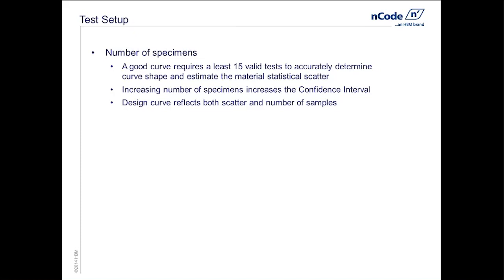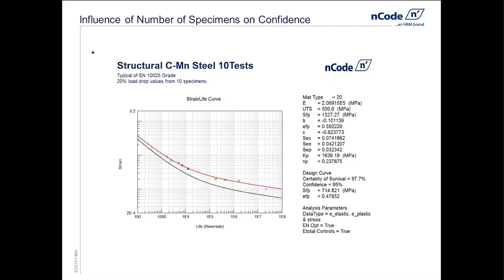And what I mean by that, here I have an example of a strain life curve, and if you look at the plot, the data points, both the blue diamonds as well as the green X's, are actual test data. These are actual specimen tests. The red curve is the regression of our strain life curve through that data. And you'll see there that we actually have scatter. Obviously, there is variation from specimen to specimen, even if they were at the same strain level.